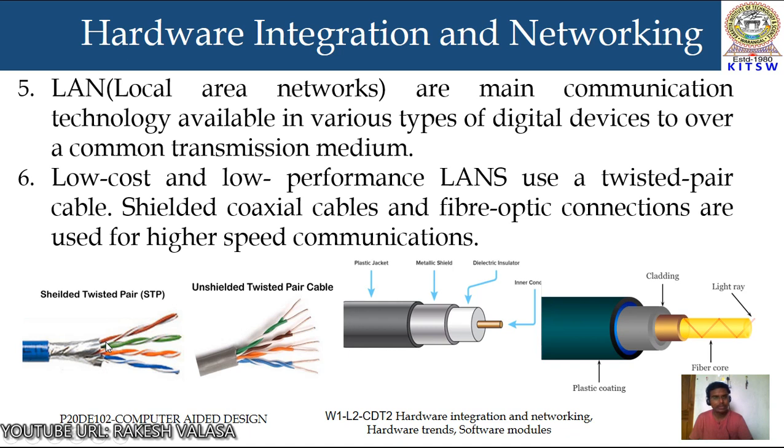Any noise that appears on the positive or negative wire of the pair would occur on the other wire, because the wires are of opposite polarities, 180 degrees out of phase. When the noise appears on both wires, it cancels or nulls itself out at the receiving end.